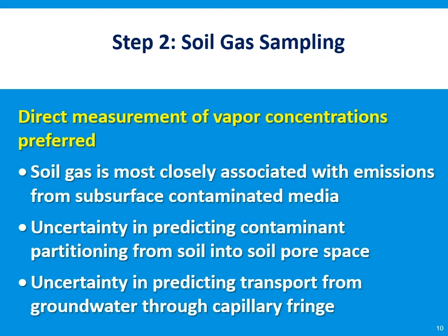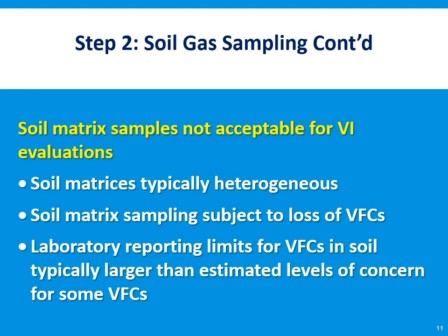Likewise, soil gas samples are preferred over groundwater samples for screening purposes. When using groundwater samples, assumptions must be made in regards to predicting contaminant transport over the groundwater's capillary fringe. These assumptions about the capillary fringe are alleviated by using soil gas samples.